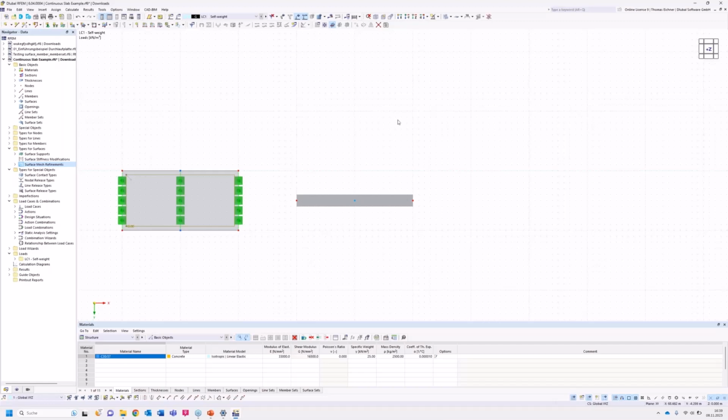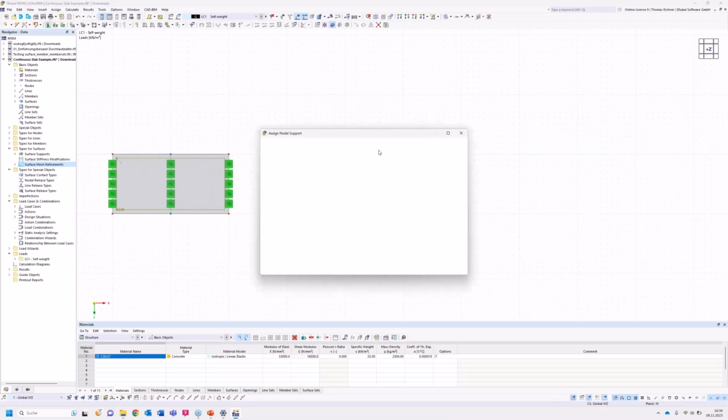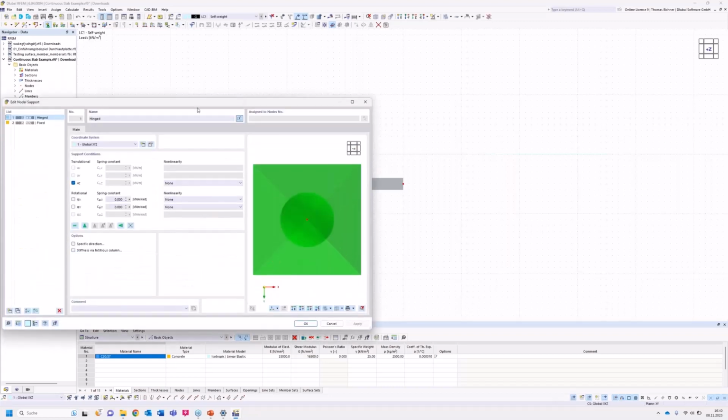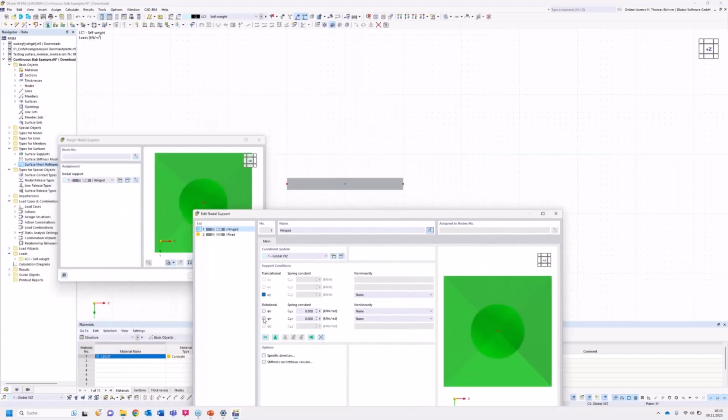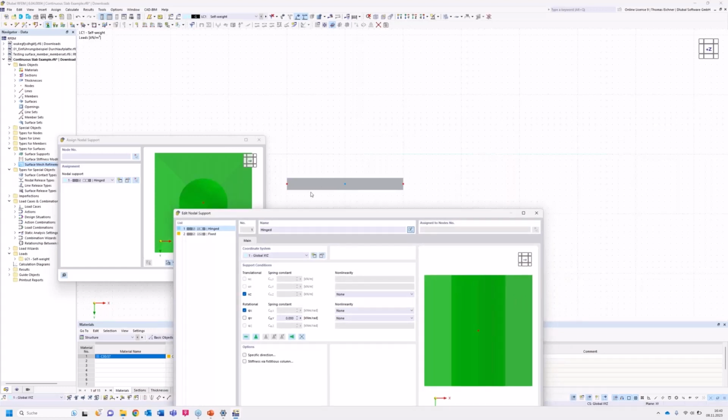Now we have this beam, we have our K matrix again. We can go for nodal supports now and add some supports to the system. One problem here is that we could use the predefined hinged one, but on the predefined hinged one, there's 1 degree of freedom which we need to block for beams, and it's the physics. So it's the rotation about its own axis. If we didn't do it, it could just rotate and fall over.